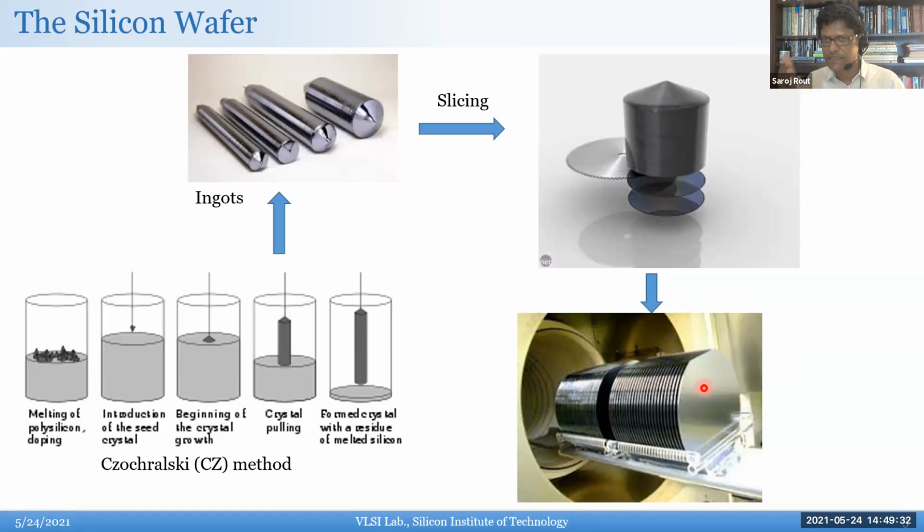And you'll see when he's inside the foundry, there are these small little caddies, like in Monsters, Inc., carrying all the wafers on top. You'll see there are carriages putting them into different places. So the foundry is a huge place, and these wafers get placed. For example, they'll grow silicon dioxide first, and then all the wafers will come out, obviously vacuum sealed and all that, and go to another place and so on.